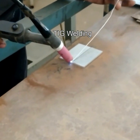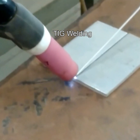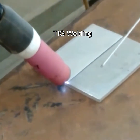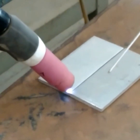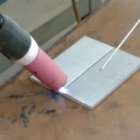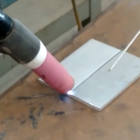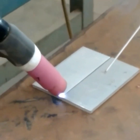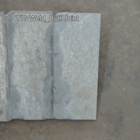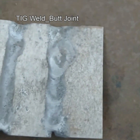You can use DC current with straight polarity to perform TIG welding, because due to straight polarity, electrons will flow in the opposite direction from the base metal to the electrode, and due to the movement of electrons, the shielding gas coming from the torch will ionize and protect the workpieces from the formation of oxides. And you don't need to use flux for further protection of workpieces. You can see the final butt joint.